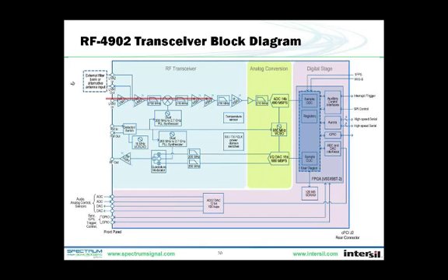So let's walk through what happens with a signal as it passes through the system. On the upper left, we start with a wideband high linearity low noise amplifier, LNA, followed by an external filter loop, which lets users select a filter or switch bank of filters that suits their specific application. We use dual local oscillators in each of the transmitter and receiver sections to facilitate fast frequency hopping in the analog domain. So having 2 for the transmitter and 2 for the receiver lets them operate independently.